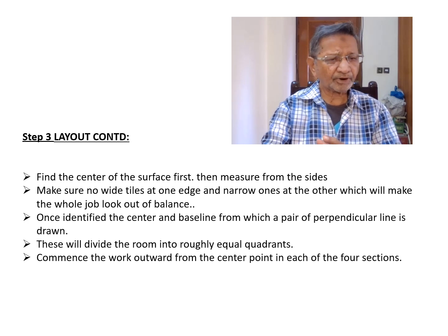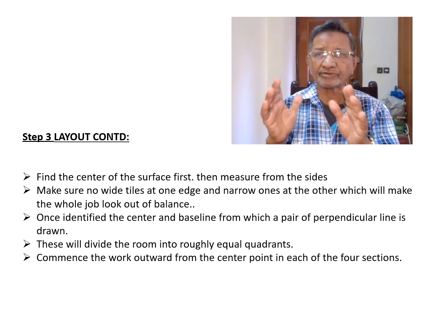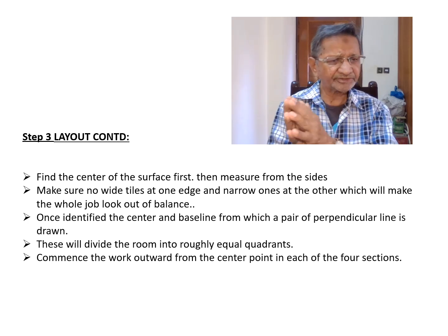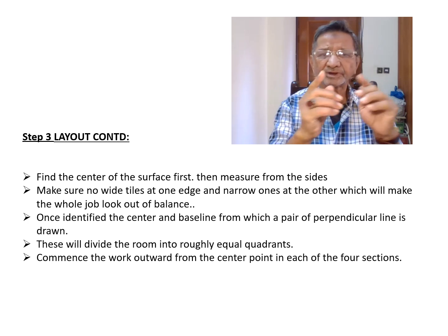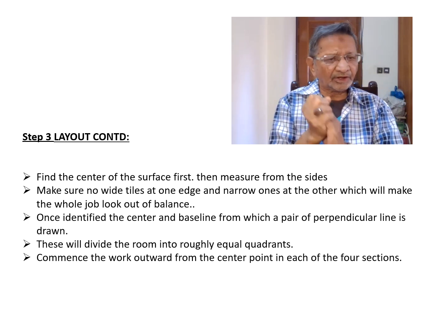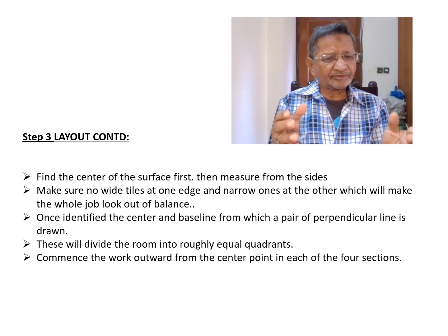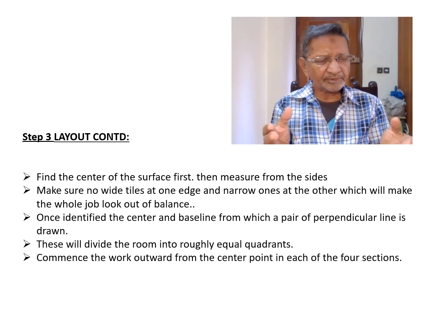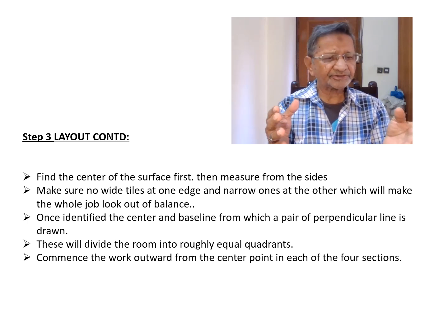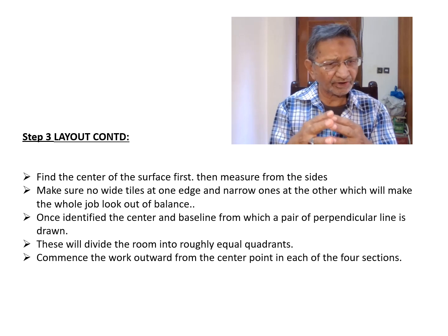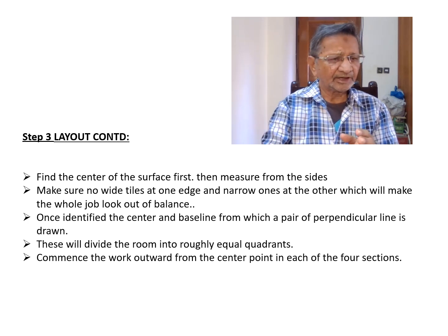Then it's important to avoid having wider tiles on one side and narrow tiles on the other, as it may create an imbalanced and uneven appearance of the tiles.